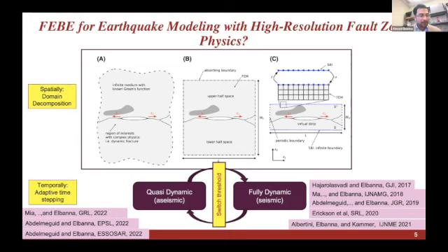And our tool to address this class of problems is what we came up with. It's called Phoebe, and Phoebe is a hybrid numerical scheme that combines finite element and boundary integral or boundary element techniques. The way Phoebe operates is that spatially, it approaches the problem through domain decomposition. So imagine you have some sort of structural complexity limited to the near fault region. What we are going to do is to encompass this structural complexity in what we call a virtual strip, and we can discretize this virtual strip using finite element, finite difference, discontinuous Galerkin,